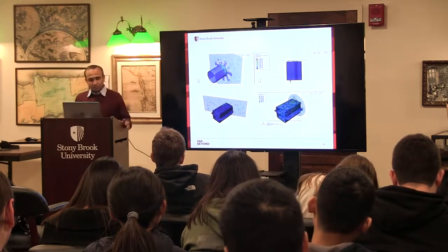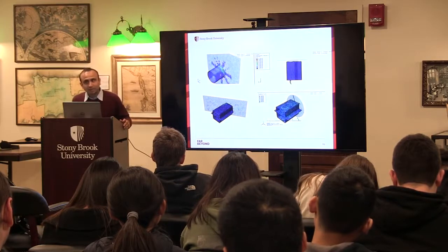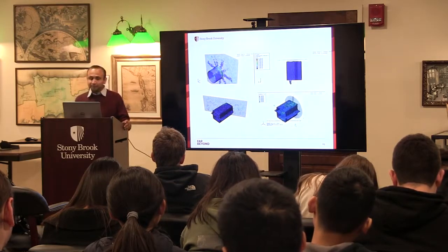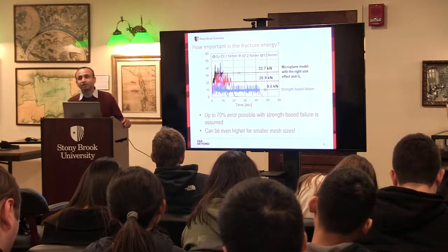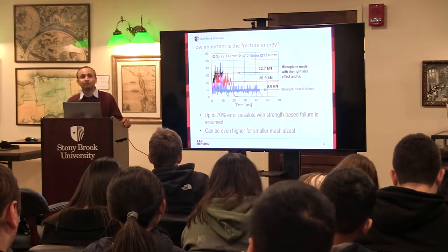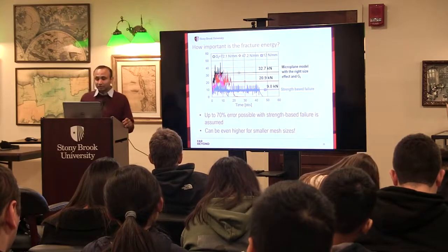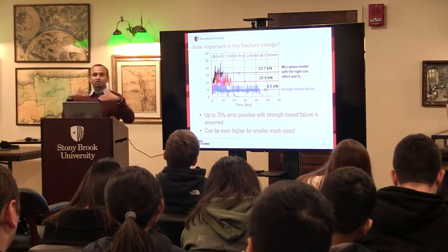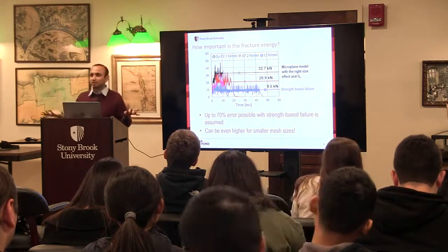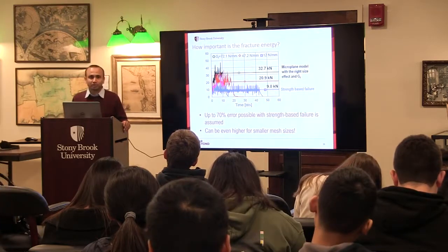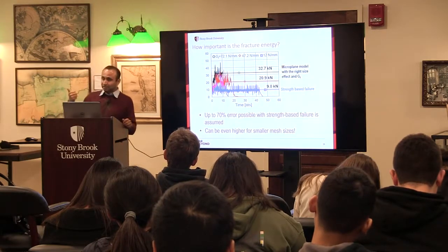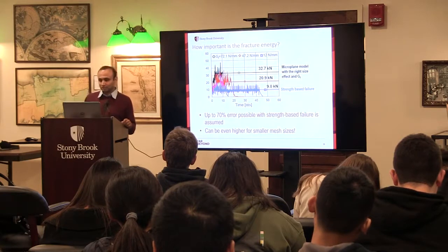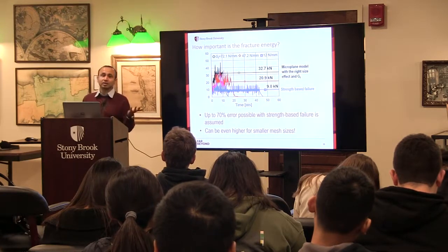So yeah, this just shows some sample simulations that we did. And there's a slide showing how important the fracture energy actually is. If you don't have the correct fracture energy in the model, it will predict a force much lower or very different than it actually is. It will directly affect this quantity. And therefore it is again very, very important to characterize it and then use it, because very large errors are otherwise possible.